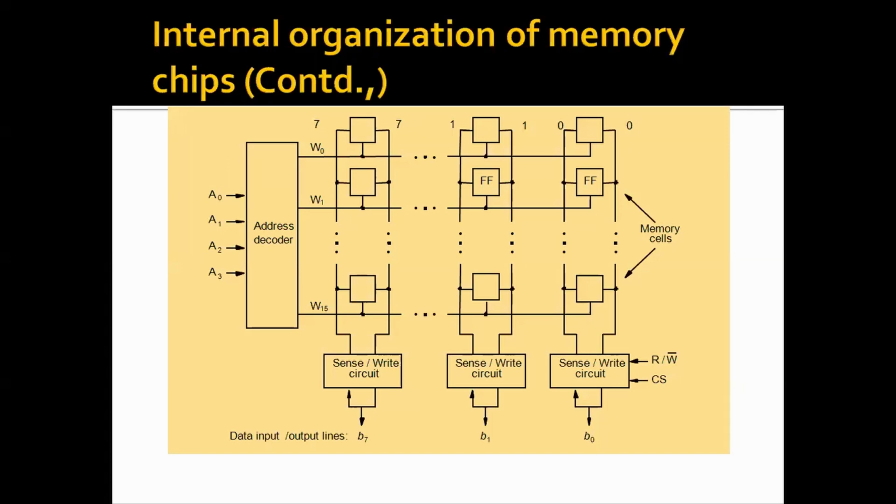The memory circuit stores 128 bits and requires 14 external connections for address, data, and control lines. It also needs 2 lines for power supply and ground connections. Here is a slightly larger memory circuit, with 1K memory cells, that is 1024 memory cells.